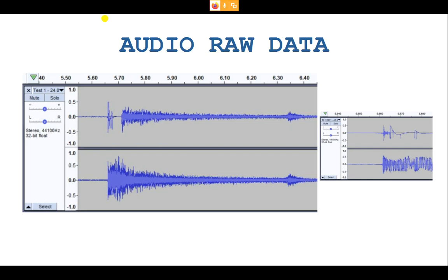Once you have the velocity of the shock, you can calculate the velocity of sound, and the ratio of the velocity of the shock to the velocity of sound gives you the Mach number of the shock. This is how you can calculate the Mach number from your shock tube. You have to do an experiment and record signals from your microphone, which is the most basic device you can use to record the signals.